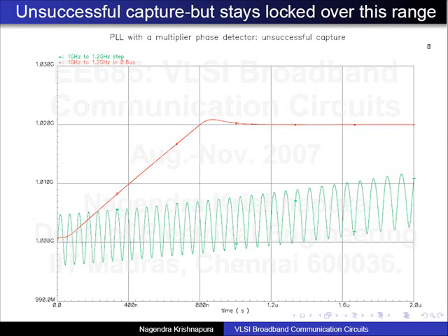That's true. The only distinction we are making here is that the phase detector will give you a sinusoidal output at the difference frequency. If the difference frequency is also attenuated, let's say it's attenuated infinitely. Okay. In fact this is a ridiculous case, but say the loop filter has a notch at some frequency and the control voltage is nulled out. Then the input to the VCO is 0, right? So it will simply keep oscillating at the free running frequency and there is no feedback.